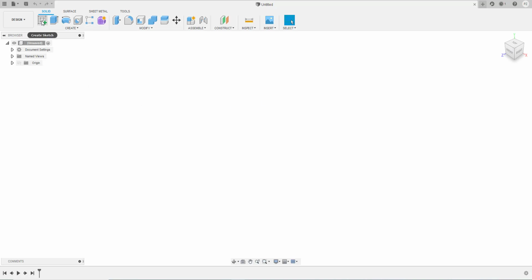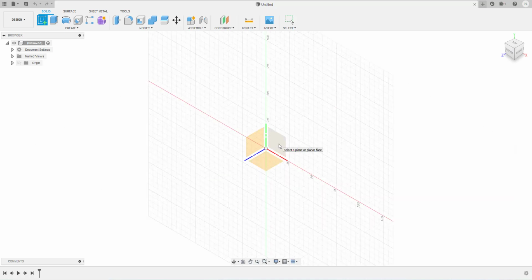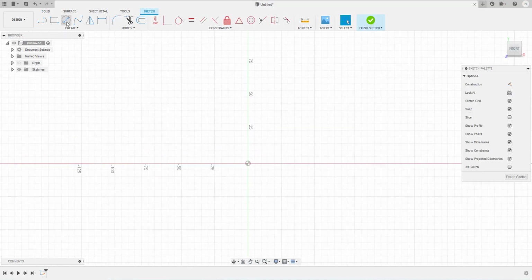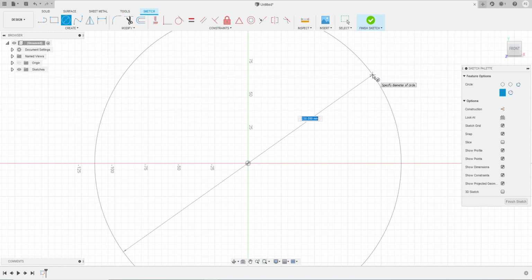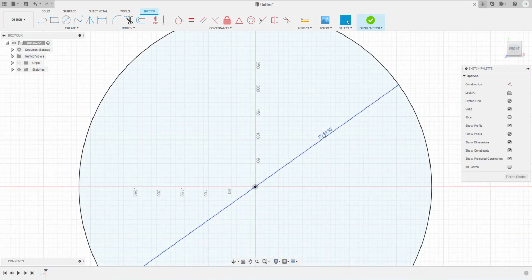We're going to start a sketch, so create sketch, and I want you to select the side plane, this one over here, and we're going to draw in a circle. Select the circle tool, click from the center, go out, and a standard size basketball is 29.5 inches. So you have to type in 29.5 IN. Otherwise, it's going to keep it in millimeters. I'm going to press enter, and it converts it to millimeters, but it is that 29.5 inches.